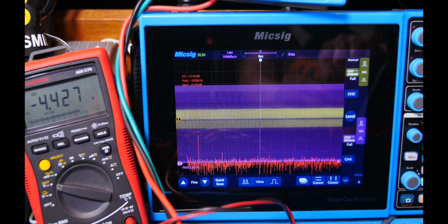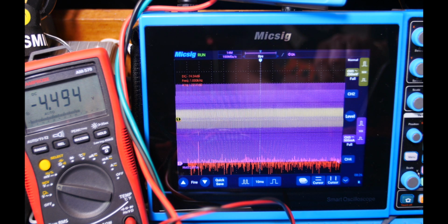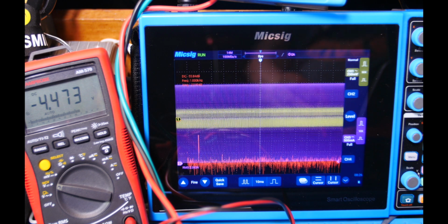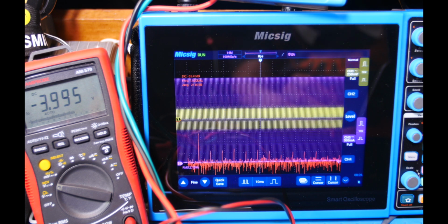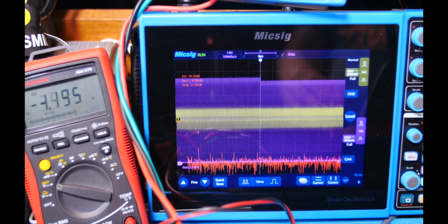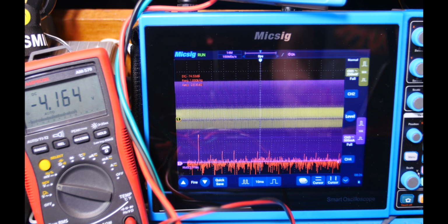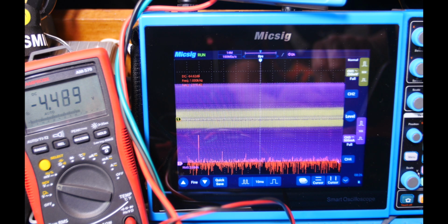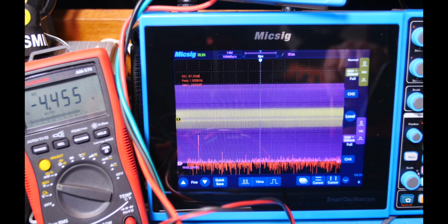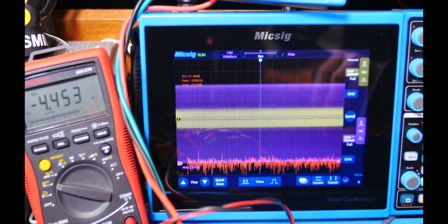Okay guys, I'm playing around. As I get about 4.5 volts here with the signal actually running through it, that's when that distortion looks like it gets pretty good. I mean, it drops down pretty low. And if I bring my input signal up, I start getting power supply distortion. I get that red clipping. So right there, I'm not getting clipping, but as I adjust my current, it'll create that clipping problem. So it's kind of a seesaw back and forth. So you really have to get the right power supply, the voltage rails that you want to run, and then adjust this compensation. But yeah, right there, it doesn't look too bad.